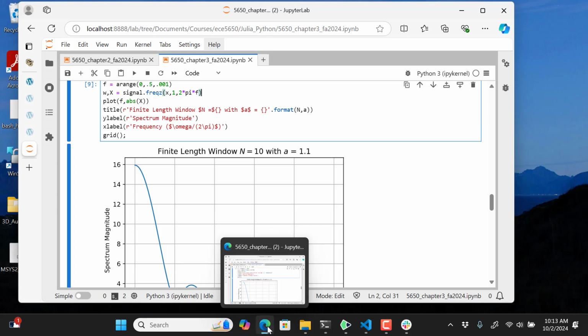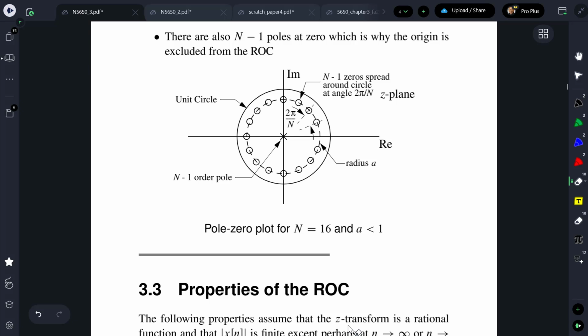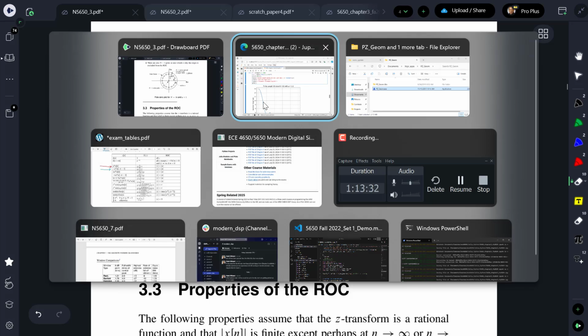Okay, so we'll come back to this and we'll see these sorts of things happen, and you've got some things in the homework problems that deal with this too. In particular, you've got a triangular shaped impulse response, which you study in the form of the convolution of two rectangles, because remember that if you convolve two rectangles you get a triangle. And we want to see what that does in the z domain. So it will be related to this. And since I'm already talking about that, let me just jump over and let you see how you could go tinker with that if you wanted to.